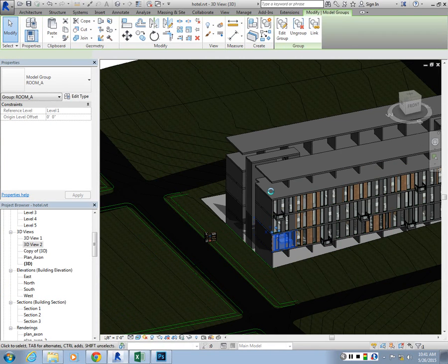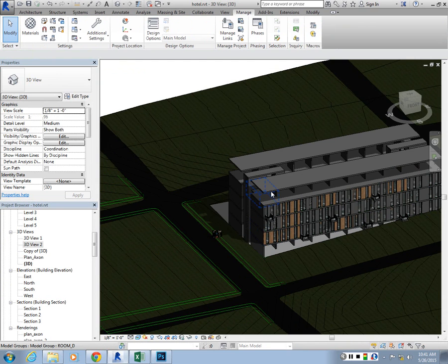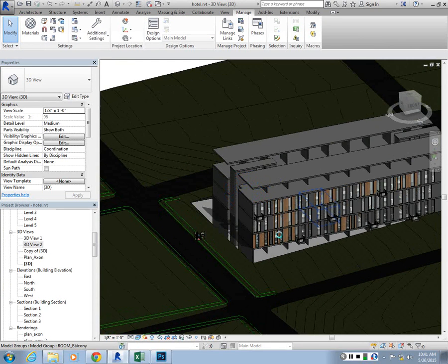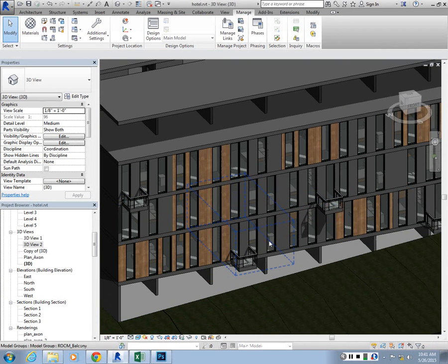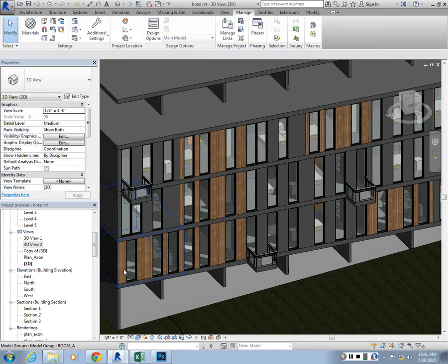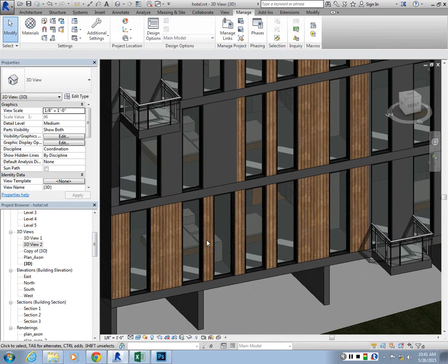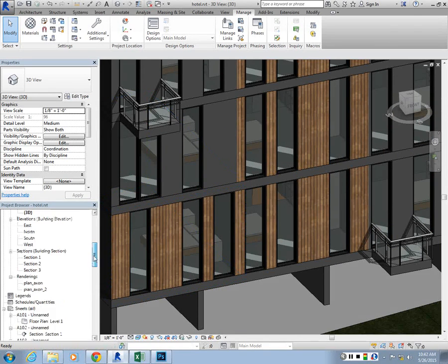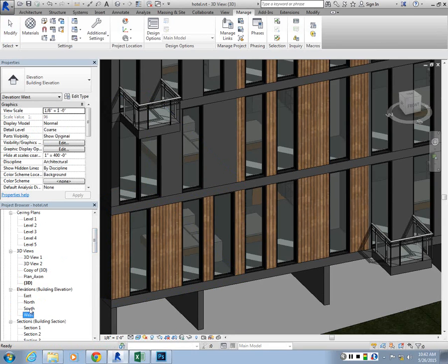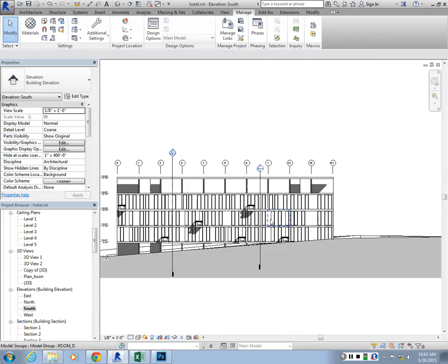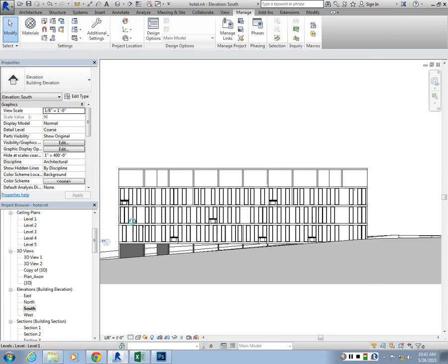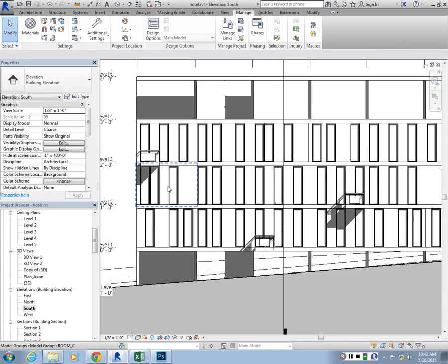Now, I basically override that exterior wall of the group. So each unit with that wall has been overwritten, right? Because I changed the material for that. Okay? So the other thing we may want to do is also to change the graphic representation of this in a 2D viewport, like an elevation. So if I go to an elevation view, like let's say the south elevation, I think that unit was somewhere here, but right now there's no fill associated to that material.